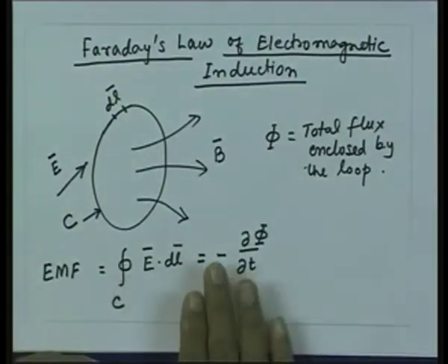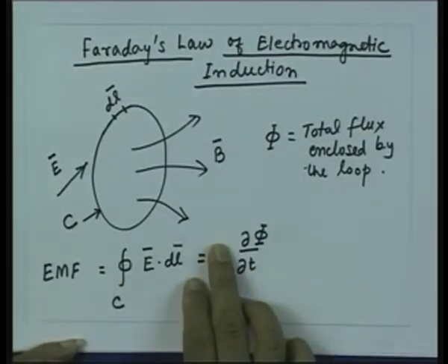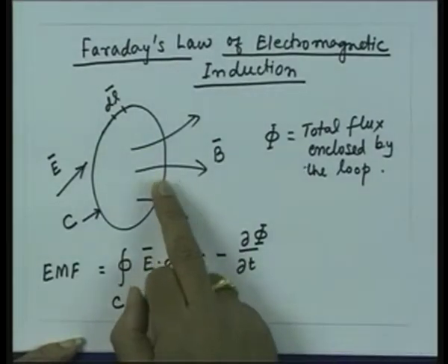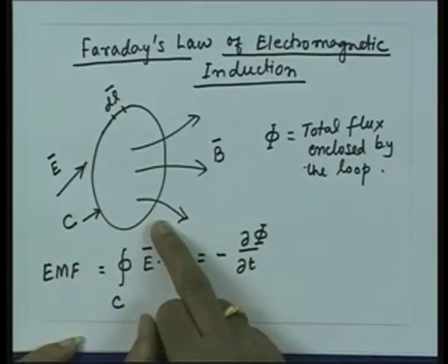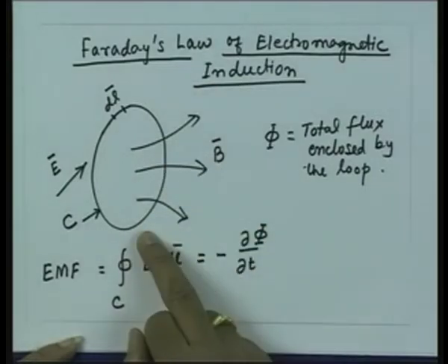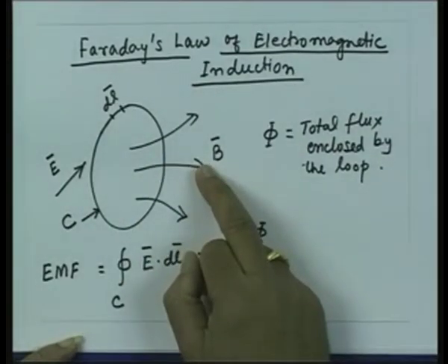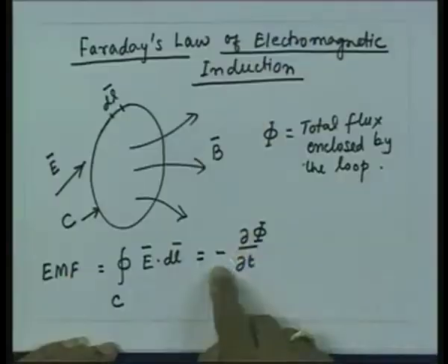Suppose the negative sign was not there, what that means is the magnetic fields will produce the EMF, which will produce a current, which will produce a magnetic field, which will add up with the original magnetic field. So, the magnetic field will increase. If the magnetic field increases, the EMF will increase. So, essentially there is no stabilizing element here, the thing will go on growing indefinitely. So, essentially this negative sign stabilizes.